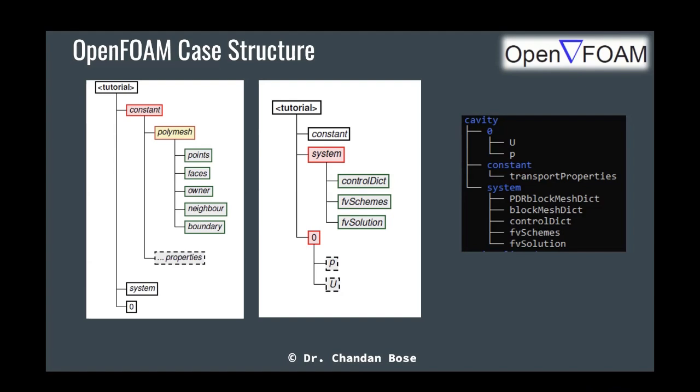In the controlDict, the first line says the solver and the solver name. So if you write the solver name, let's say icoFoam, but then you call another solver, it will show you an error, because your code doesn't understand which solver you are calling and what type of problem you are going to solve. Clear? Any other question related to the tutorial? Because when we'll be doing the next things, you need to understand what things you need to mention to change the boundary conditions, solver setup, etc.